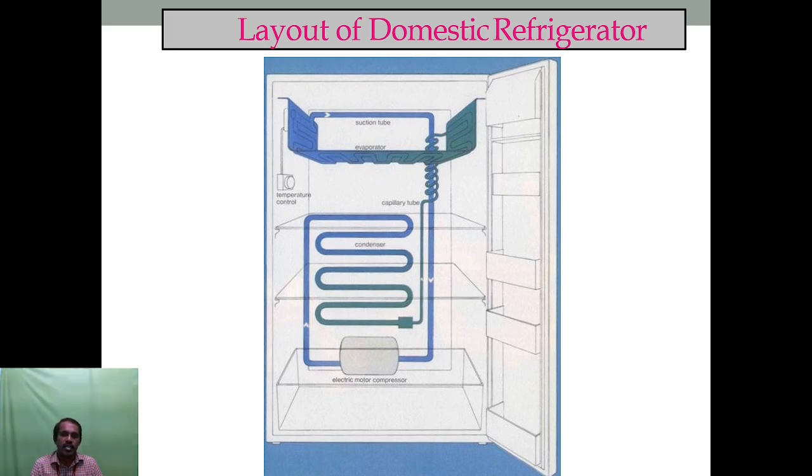The condenser is a cooling medium, a heat exchanger. The condenser converts the high pressure vapor to liquid form, so the entropy totally changes. This then goes to the expansion valve. The expansion valve only reduces the pressure.